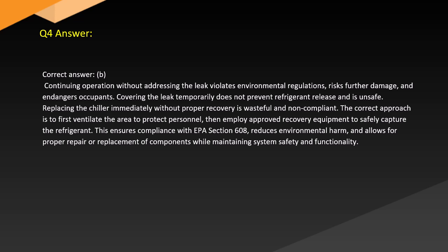Answer. Correct answer. B. Continuing operation without addressing the leak violates environmental regulations, risks further damage, and endangers occupants. Covering the leak temporarily does not prevent refrigerant release and is unsafe. Replacing the chiller immediately without proper recovery is wasteful and non-compliant. The correct approach is to first ventilate the area to protect personnel, then employ approved recovery equipment to safely capture refrigerant. This ensures compliance with EPA Section 608, reduces environmental harm, and allows for proper repair or replacement of components while maintaining system safety and functionality.